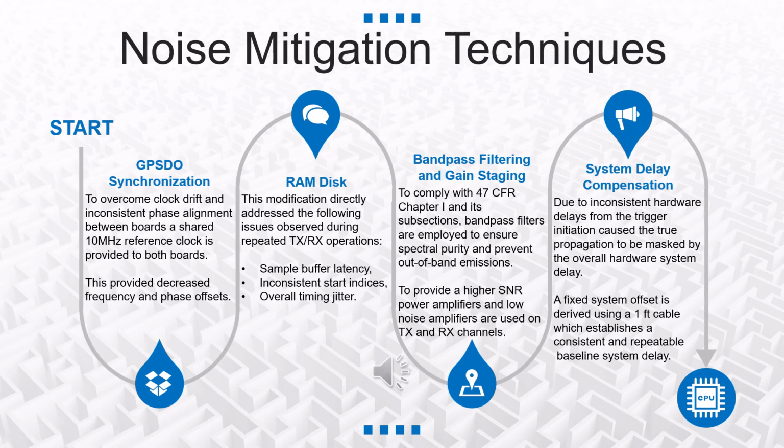Also, there was bandpass filtering, and that was specifically to comply with FCC regulations. And there were gain stages used, power amplifiers and low noise amplifiers, and that would help boost the signal to noise ratio. And then lastly, the system delay compensation, and that helped to correct for fixed hardware issues and trigger latency issues.